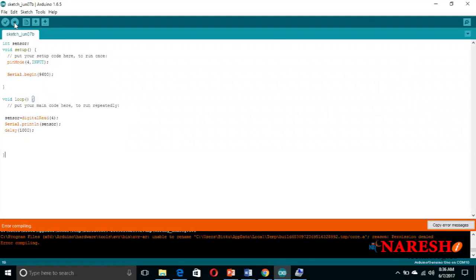Today, what I did: how to read the sensor value, LED blinking, and DC motor. For reading the digital value, the command is digitalRead. If you want to read the analog value, the command is analogRead. By using the different commands, we can read the value of the sensor. And then after putting some if-else commands, we can control any device from the value of the sensor.